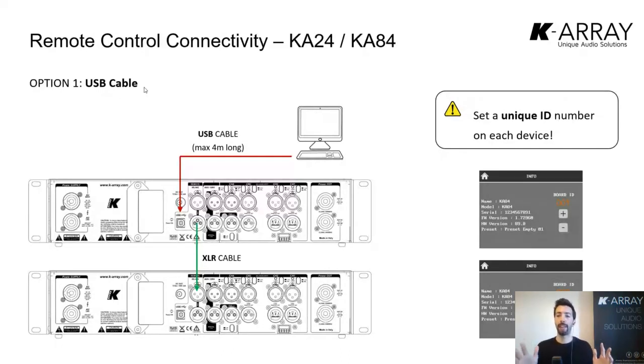Now, USB cables have a problem. Usually they cannot be longer than a few meters. If you have a longer USB cable, the signal may drop and you may lose communication. There are some special kind of active powered USB cables that can be longer, but most of the time, if you use a standard USB cable, it should not be longer than a few meters.